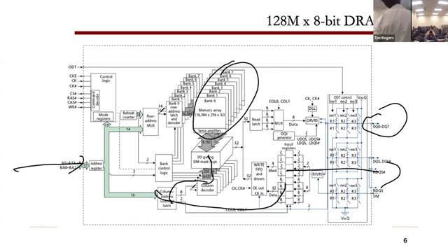I think the first number here on the memory array is the page width. So 60, is that right? No, the page width is 8K. Okay, the page width here is 8K bits. So every time you open it up, you're getting 8K bits out of the sense amps.